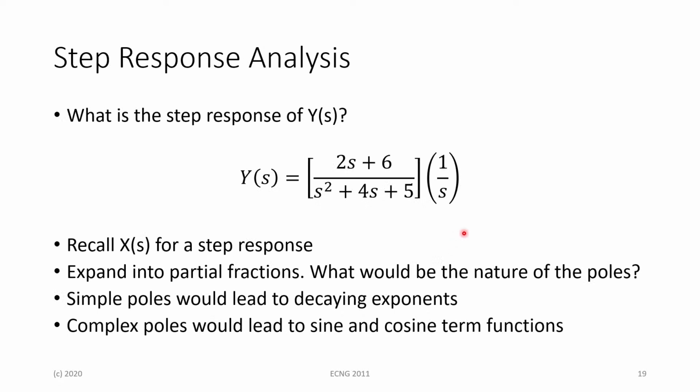There's also some step response analysis that you can do for block diagrams. If you remember, your step response was u of t in the time domain for x of t. But when you transfer this into the Laplace domain, it's going to be 1 on s for x of s. Once you have this in this form, you can multiply out accordingly and expand it into partial fractions. Once you have the partial fractions, you can obtain this back in terms of y of t, and then you can plot y of t to see what the response is going to look like.